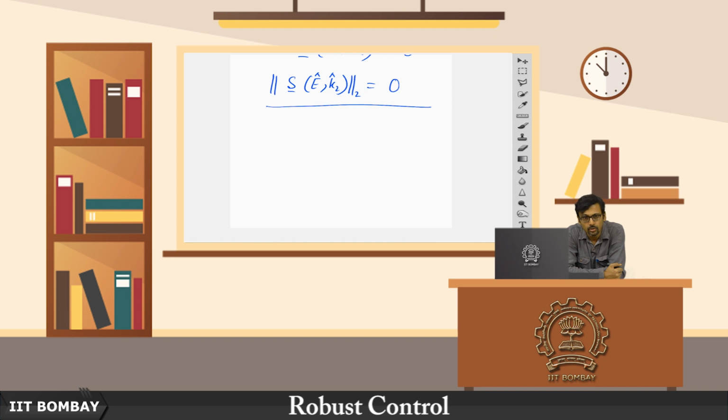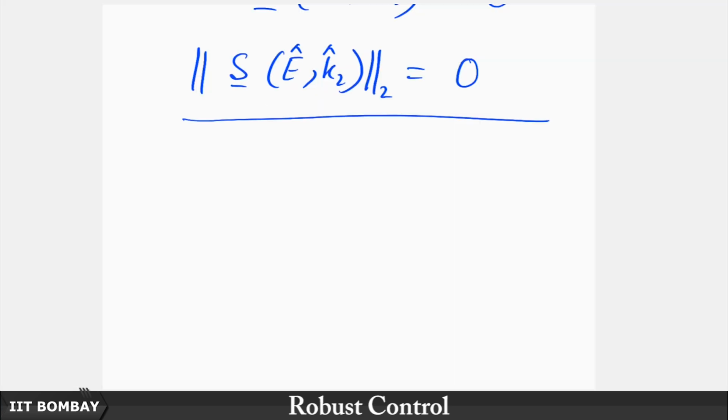Okay? Although I must tell you that the next problem we are going to look at after this one is over, that is the H infinity problem, where we shall be entirely dealing with LMIs. This H2 optimal control problem need not require going via the LMI route. Nonetheless, just to give you a unifying flavor that the H2 optimal control problem can be solved using this Riccati operations and the Hamiltonians that we have defined, but also it can be solved using the LMI approach.